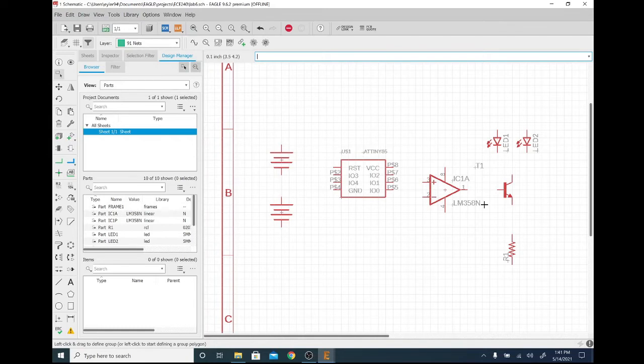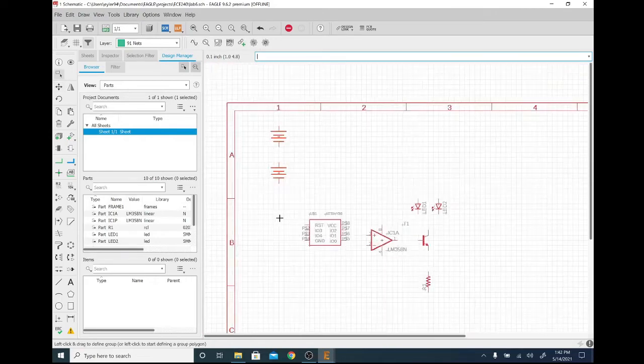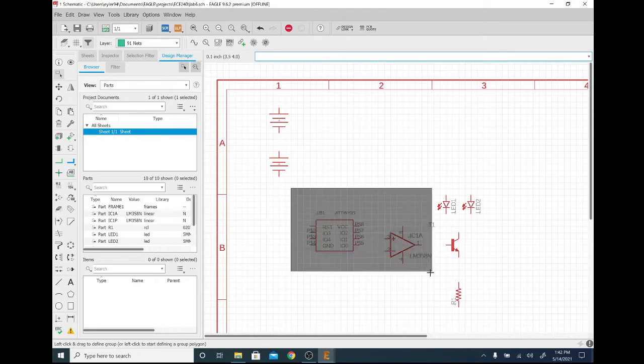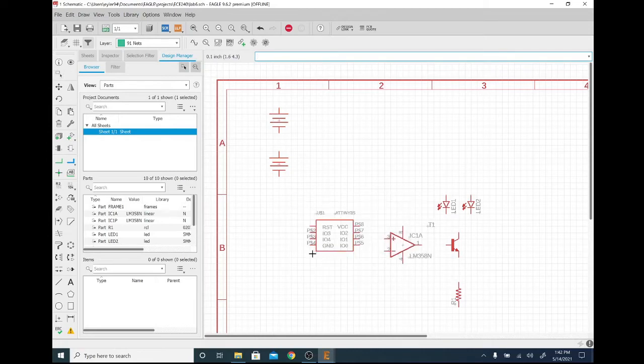All right, so all of our parts have been placed. I'm going to move these around just a little bit. So with my box select, I can select that little anchor point right there and drag those up. And what that does is it gives me a little bit more space to work around. So I know that needs to be over there. That guy can move that way a little bit. Everything else seems to be all right. This guy is the label for that transistor. I'm going to move it a little closer just so it's a little more readable. And I think that's actually pretty good.